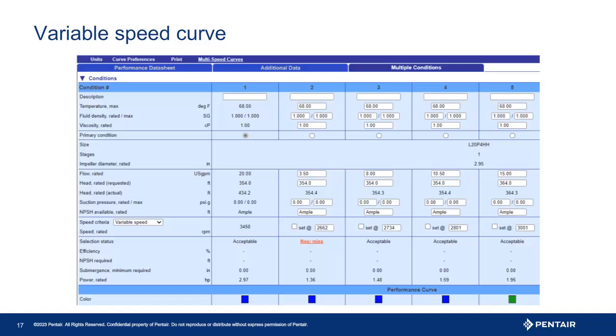Understanding total dynamic head allows you to explore the system through the lens of a variable speed drive. Here I left the primary at a static or constant RPM to show across the line running of the pump. Next you see various running conditions. A single shower head running 3.5 gallons per minute. A washing machine running 10 gallons per minute. All three showers running a combined 10.5 gallons per minute. And finally, I took the time to recalculate the total dynamic head for the irrigation system, making the curve green to show up better. Recalculating the system, one thing that pops up is the near miss of the single shower at 3.5 gallons per minute.